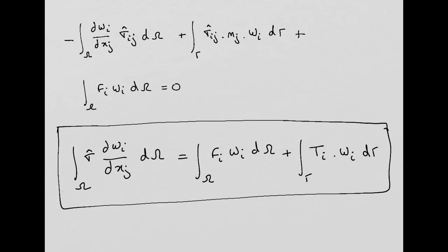This is a very important result, which, again, doing a very quick summary, why we arrive at this. Basically, our starting point was the equilibrium equations from elasticity, which is a set of differential equations. The second step was to get an approximation function for sigma, which we didn't define yet, but I just replaced my exact sigma with sigma hat in the differential equation, and by doing that I got the residual.